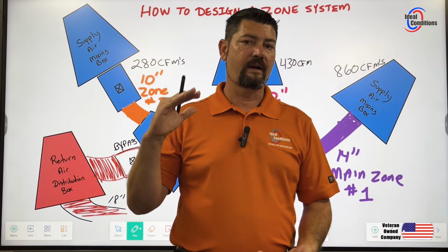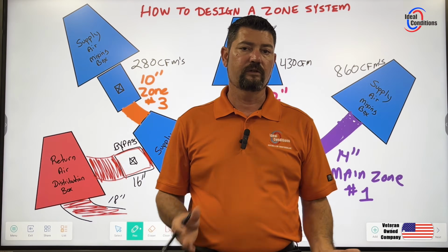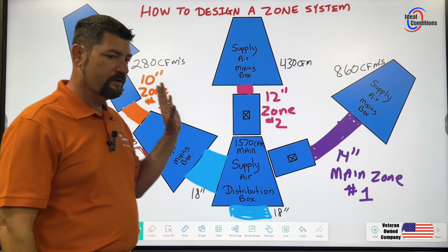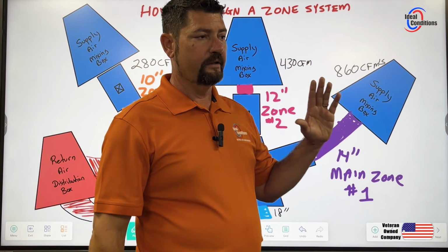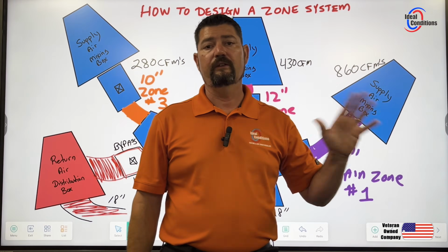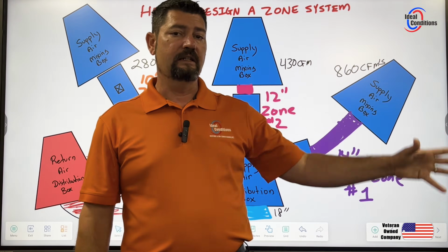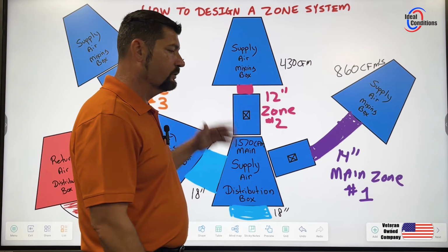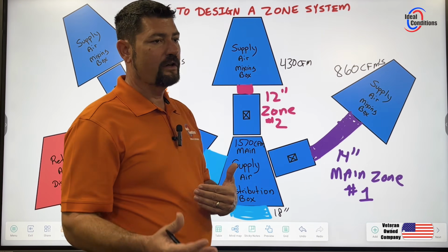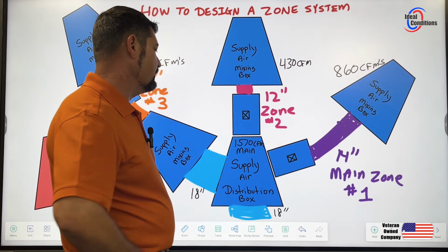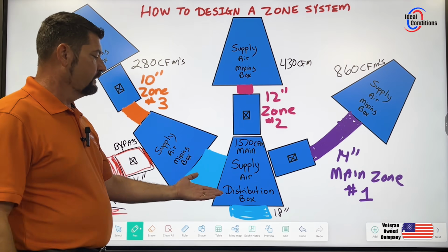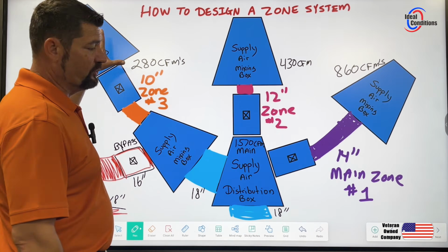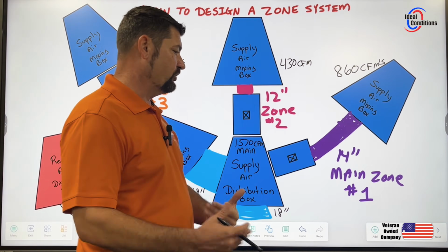So when that temperature starts to drop down, there's not enough heat on that coil to boil that liquid off, so you don't return back in a liquid state to that compressor. You want to make sure that that discharge air temperature sensor can tell that zone board that it's reading a low limit, so it can cycle off that condenser unit and put it into a 5-minute time delay. Basically, after 5 minutes, if one zone is still calling, it'll just come back on automatically. It just turns it off, kind of starts the clock for 5 minutes before it brings it back on. That gives just enough time for when that condenser shuts off, for that coil to warm up a little bit, and that zone may even shut off while that DATS has shut that condenser off.